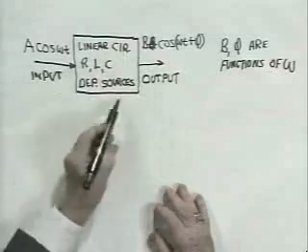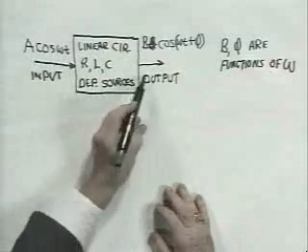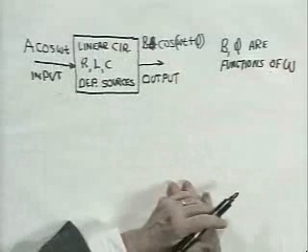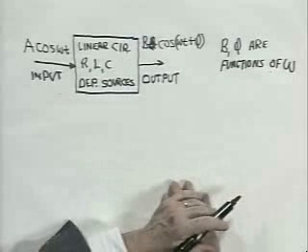So we have a sinusoidal excitation, we get a sinusoidal response, the magnitude B and the phase angle phi of that sinusoid, that is the phase angle with respect to the input, are determined by the network and are generally functions of frequency. Now, if we proceed with the differential equations of this network with a sinusoidal input and search by straightforward analysis techniques for the response, that's a perfectly straightforward thing to do.